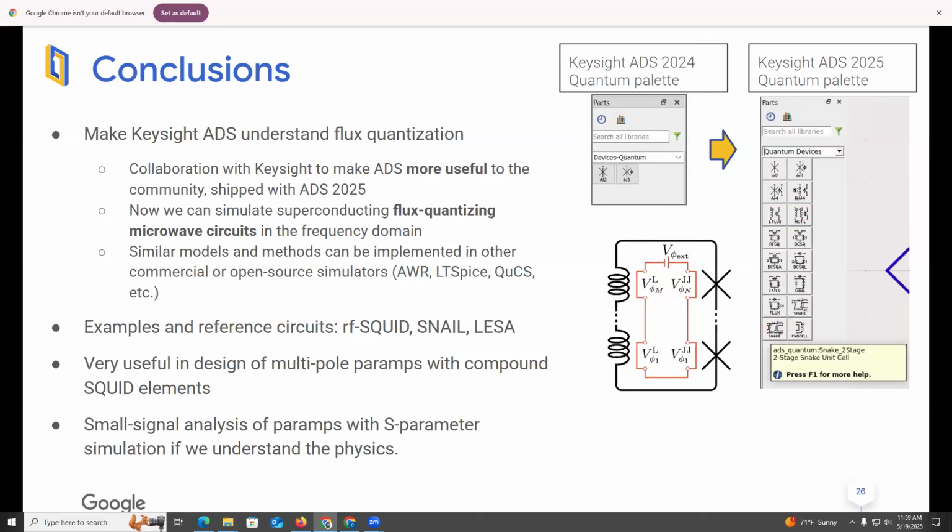We're abstracting them to symbols in a schematic. So I think this complements EM simulations, and you have to iterate. You have your design at the circuit level, then you try to implement it, as Eli said this morning, as layout. You simulate the layout in ANSYS HFSS. You get values that you can plug back into your simulation. You get parasitics, and you can see if this thing still works.